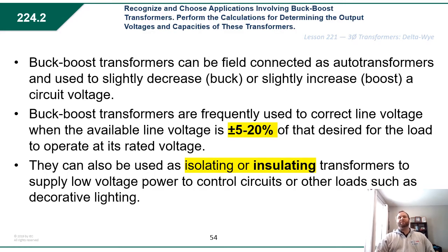Buck boost transformers can be field connected as auto transformers to buck or boost the circuit voltage. They can also be used as an isolating or insulating transformer to provide low voltage power to control circuits or other loads such as lighting or nurse call stations, you name it. So these transformers are a smaller kVA transformer that are designed to be used in multiple fashions, whether it's an isolating or insulating fashion or a buck or boost fashion.